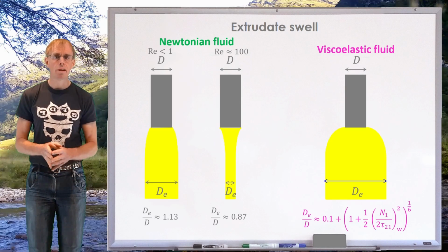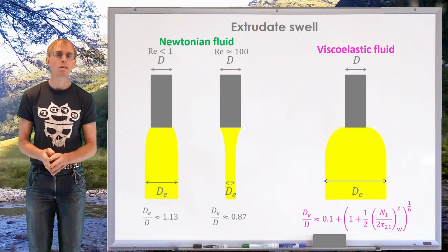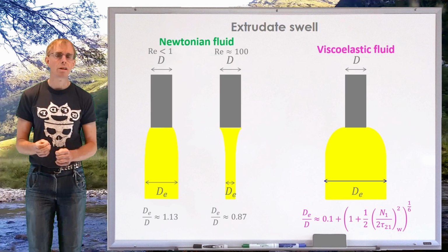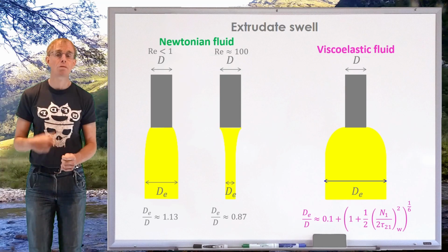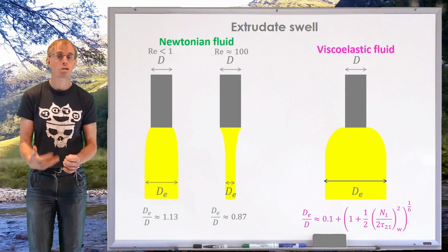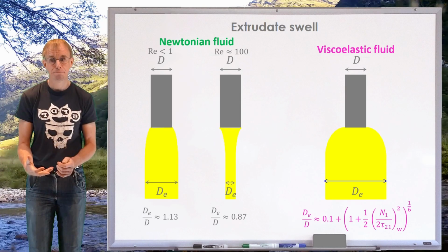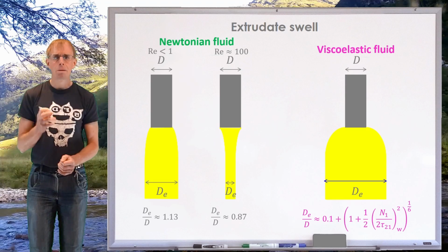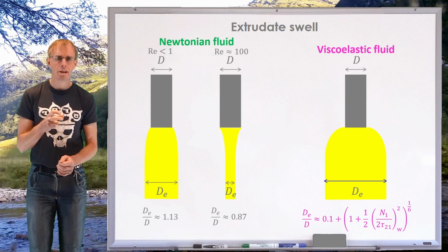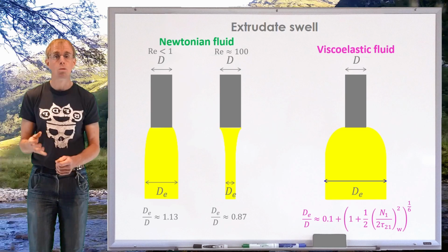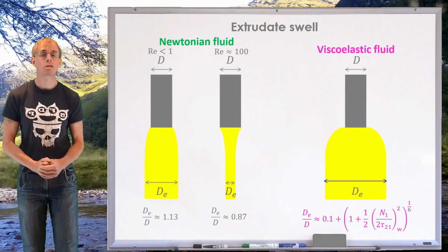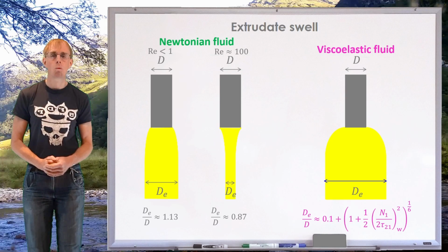And so we have to be rather careful if we're shape forming complex materials, because the die design may be different for different materials because of the rheological properties of the materials and the way they store stress and the way they swell. So complex cross sections in extrusion dies are quite difficult to get right. It's quite an art form, but there's a lot of computational tools in the modern era that allow us to design that with a little more care.